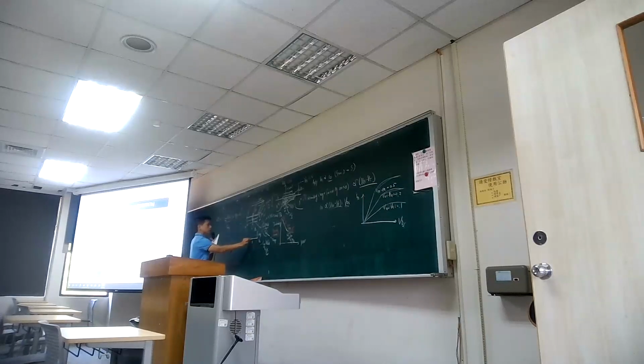That means you get a linear interpolation of the voltage difference between source and drain, and that assumes we have a uniform doping of this semiconductor. So there's no defect, it is an ideal case. If you apply the positive voltage, what is the direction of your current? The current will flow into the drain to the source side, so the current direction will be ID along drain to source.